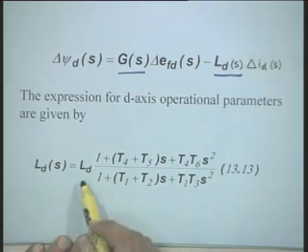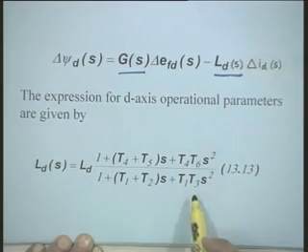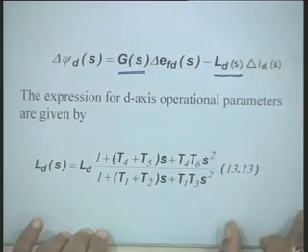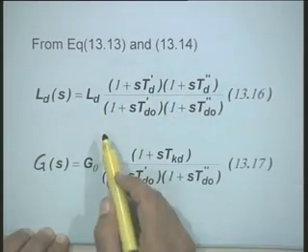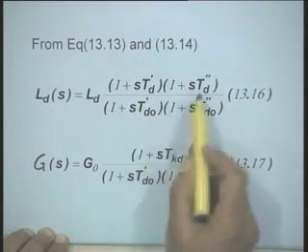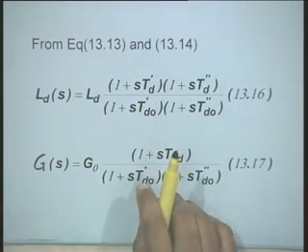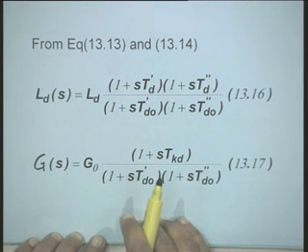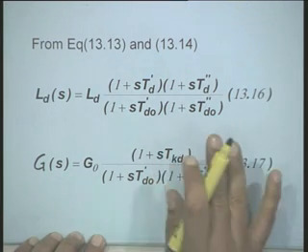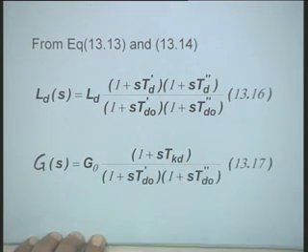This LDS is written as LD multiplied by this expression, and we are now writing LDS in this form in terms of these time constants, while these are our standard parameters, and as we will see, they can be measured from certain tests which can be conducted on the synchronous generator.